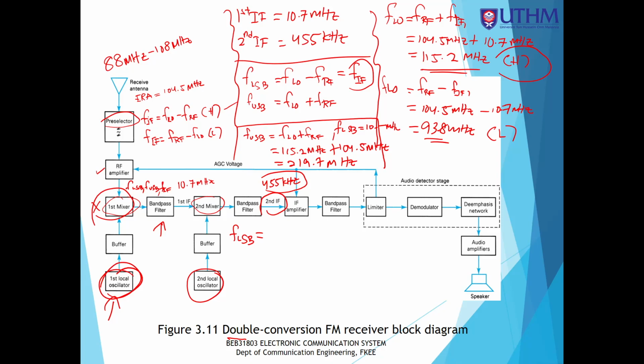So the lower frequency band, FLSB, produced by the mixer is actually equal to FIF2, which is FLO2 minus FIF1, so it becomes FIF2. While the FUSB is equal to FLO2 plus FIF1. So this is FLSB and FUSB, the frequencies produced by the mixer.